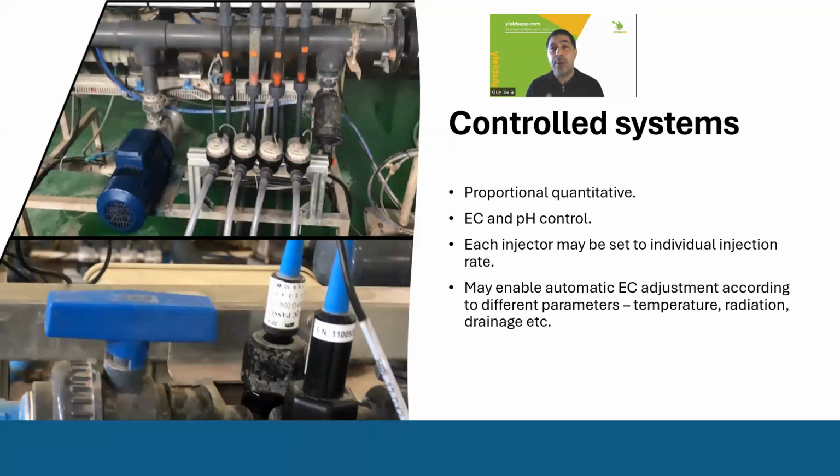Think about water with high calcium and magnesium. If your water source contains high concentrations of calcium and magnesium, then you might not need to use calcium and magnesium in your nutrient solution, and that saves you a tank. So this can also help you design your system, because otherwise you might spend money that is not necessary. So one is to know how many injectors we need, how many tanks, and how many valves we want to use. That's also important. Remember, we talked about the injection ratio.